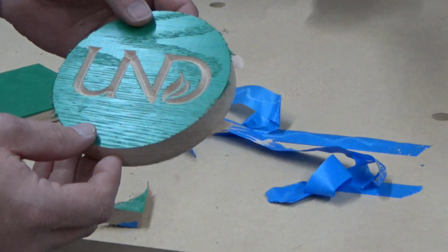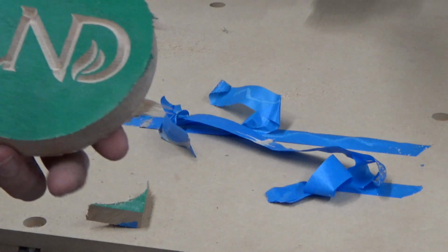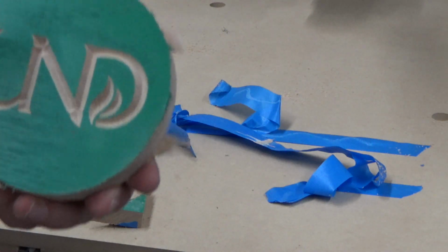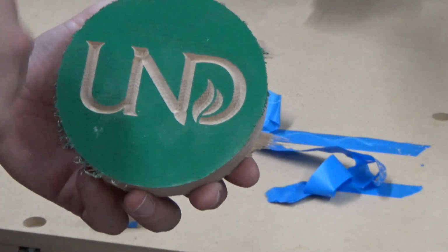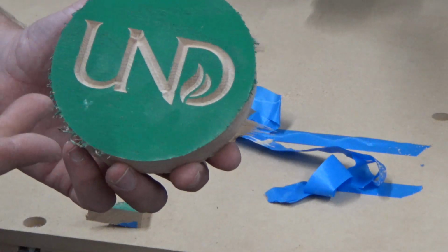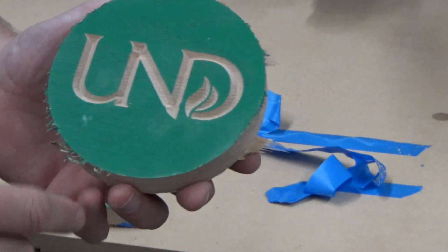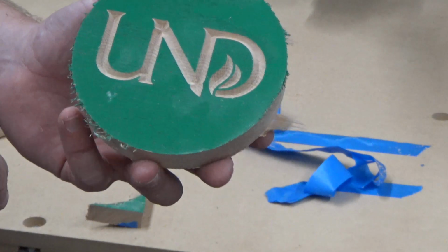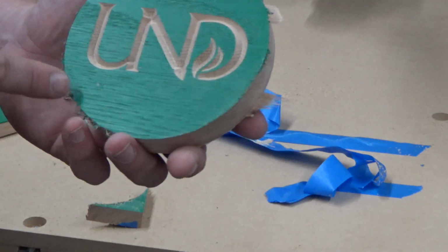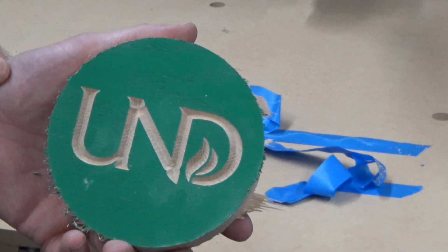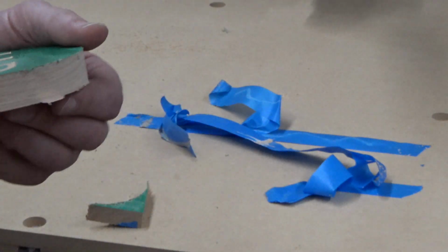That's an example of us setting up and carving a V-carve, making that UND logo. Just keep in mind, if you're making individual toolpaths, it's best to make a file that just does the outside, and then make another file that just does the V-carving, and upload those. And once you've set a 0,0 on a certain corner, it should keep track and remember where it was. Now, the only problem with that is if you were to shut down the machine and it loses that 0,0 location, then we run into some problems. But this is a pretty decent way to do it.